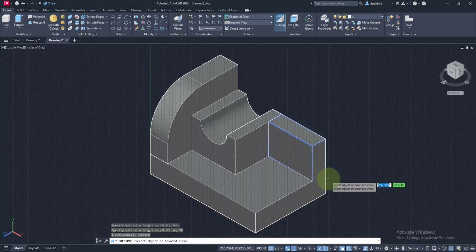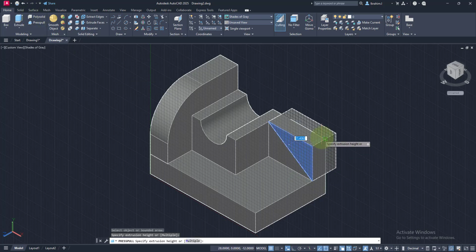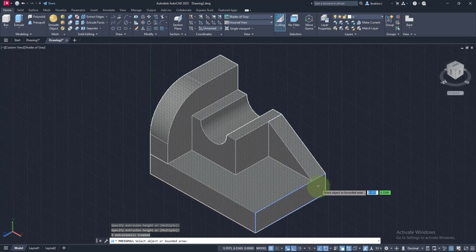Can you see that? Now the next thing I want to do, I want to split this. I know that it's not the full shape that I have, right? I'll go back to my line command. How powerful can line be in this AutoCAD? I'll go to this edge and just get it down to this edge, guys. And what am I looking for again? Guess. Press Pull. Thank you so much. So I'll select this side of the design. I'll also take it to the other end, and I want to close it to this end. You can see that I've chopped that off, and then we have our design still working fine for us.